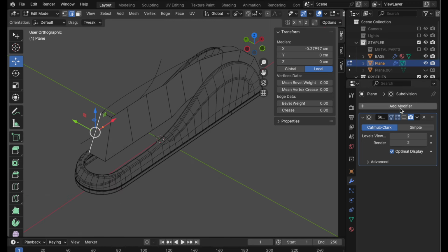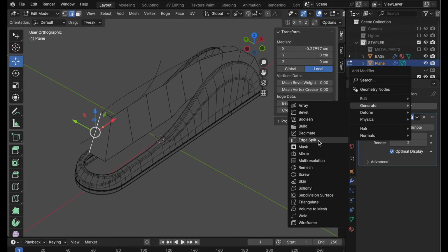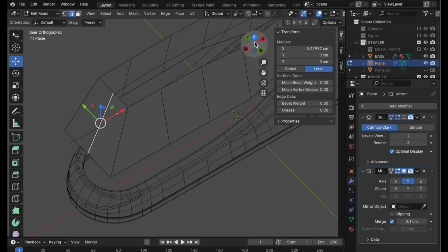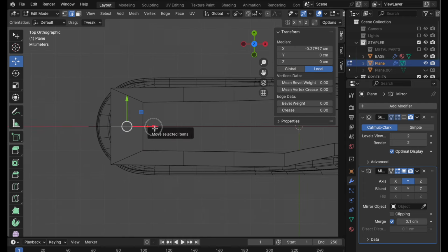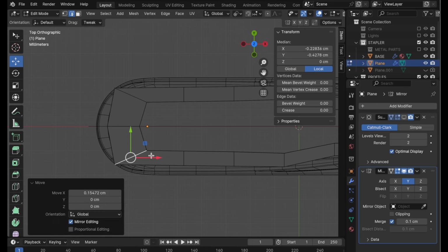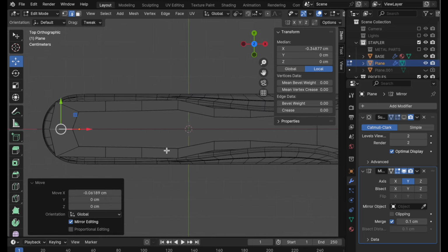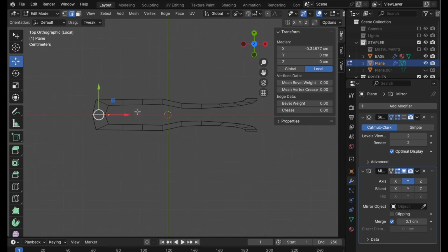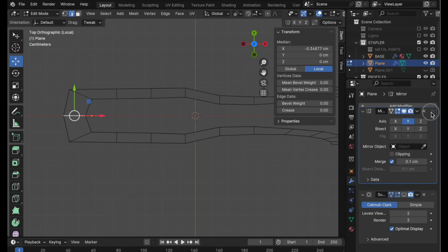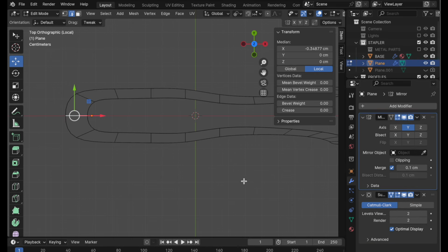Let's go ahead and add symmetry. So we come over to generate mirror along just the y-axis. I've got this edge selected. So if we look at this in the top, I want to move that forward. In fact, I think this here, I want to pull that back just a little bit, just to round that. But I'd really like to see it with the subdivision applied. Press the backslash key to isolate this, and let's move the symmetry up top, and then turn subdivision back on.